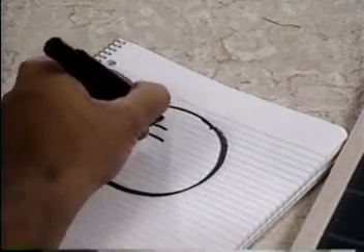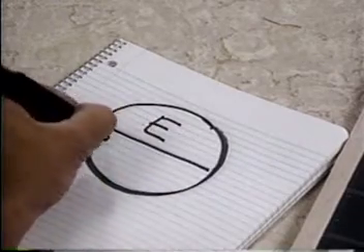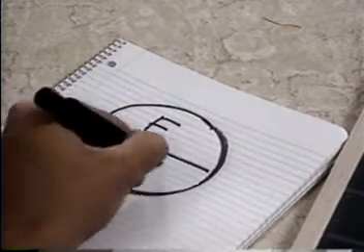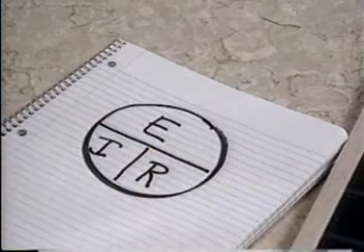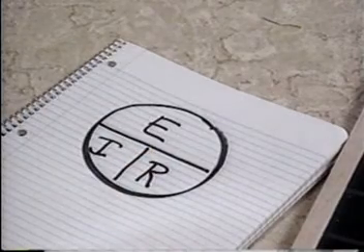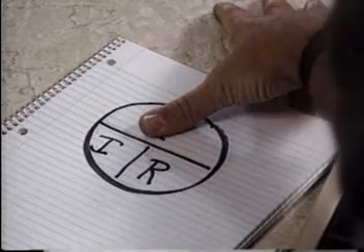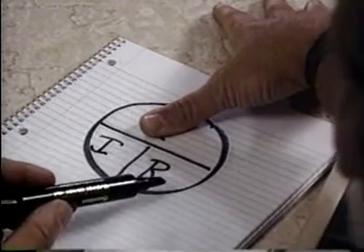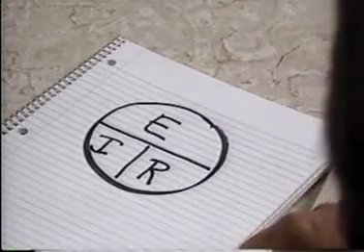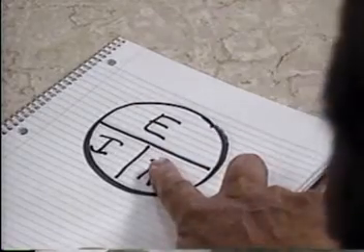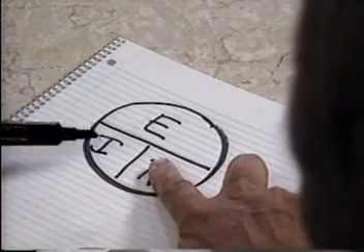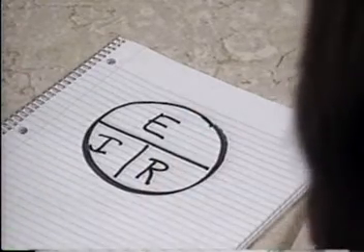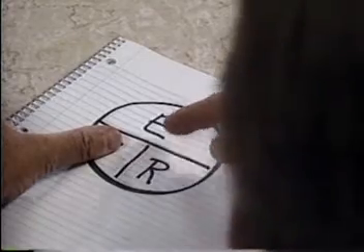Here's a little trick that will help you remember how to use Ohm's law. Draw a circle and write the letter E in the top half, with the letters I and R below. Now, if you want to solve for E, just place your thumb over it and solve for what's left: I times R. If you want to solve for R, just put your finger over it and figure out E over I. Finally, if you don't know I, cover it and solve for E over R.